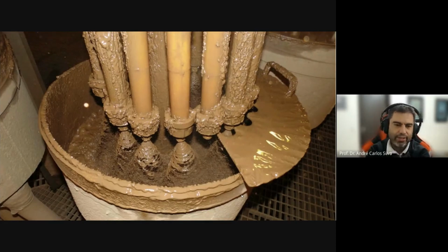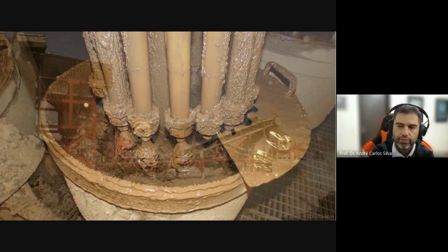If you take a look at the hydrocyclone and open this, you're going to see something like this. It's important for you to study this profile over here. According to the profile, you can see if your hydrocyclone is working as it should, or if it's working poorly. And this one is the one in standby that I mentioned to you. It's not working. This picture was also taken at the phosphate company.